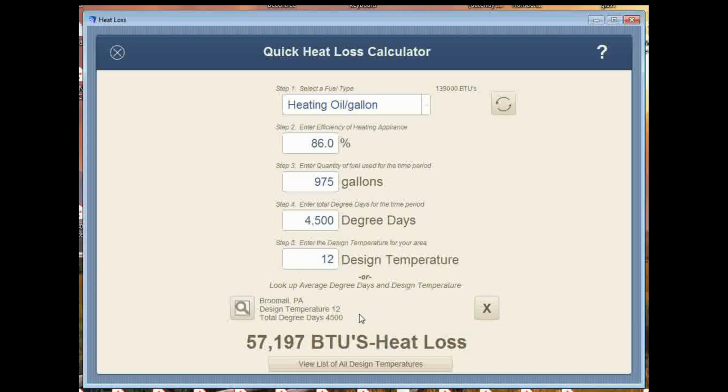Now for heating oil, you know, you don't get appliances this small anyway. So if you're under 65,000 BTUs, they get the smallest one for heating oil. And this happens to work out pretty well. I do have a couple people using it, and they say it works great for heating oil specifically. But these numbers are actually from my house, and when I did this complete heat loss on RightSoft, I came out with like 56,000 BTUs. So I think it does pretty well, especially for heating oil.